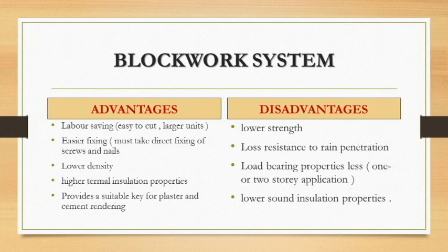The disadvantages are lower strength, less resistance to rain penetration, and lower load bearing properties, so the construction applies this blockwork system only for one or two stories.